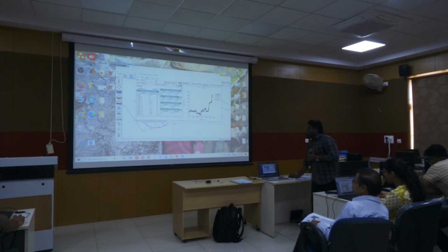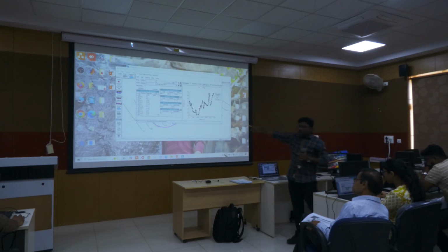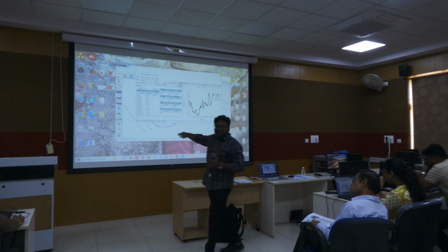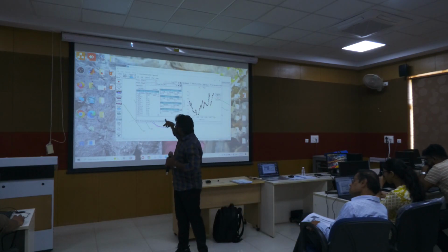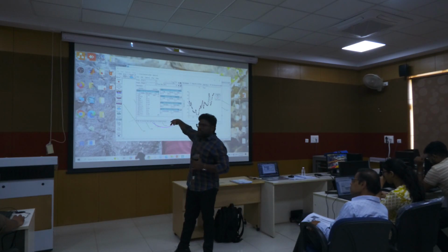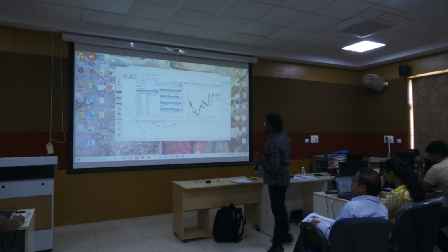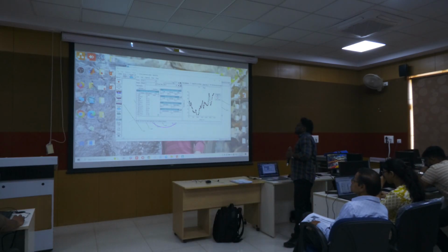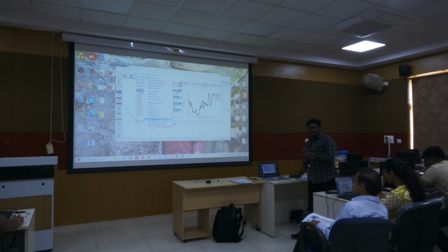For example, see, we are assuming that roughness is the same throughout the cross section, right? So we need to eliminate this column. Okay. So to do that, go to options. Here it is enabled. That's why that column is highlighted. Disable it. Click yes. Now you see that column is eliminated. So like that you do it for all the cross sections, here, one by one.